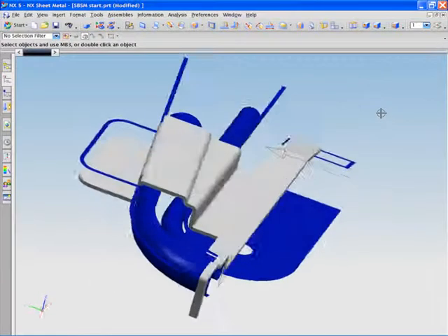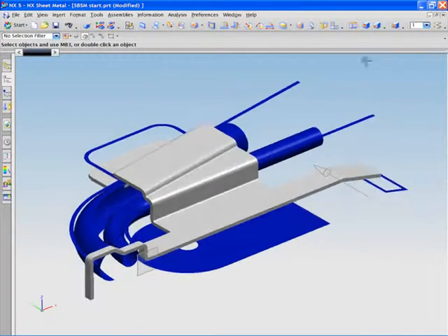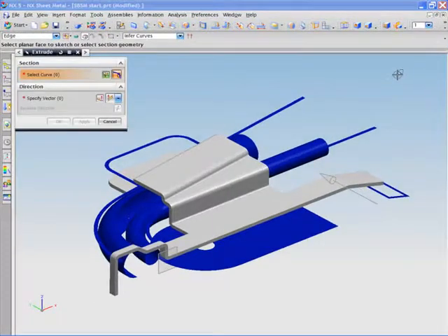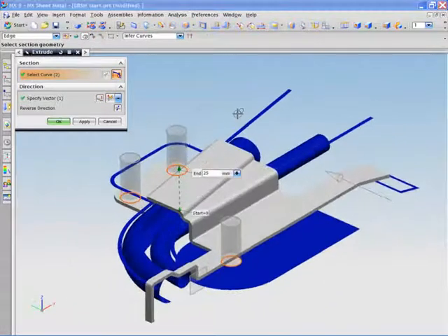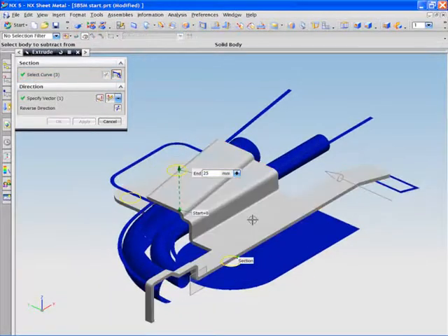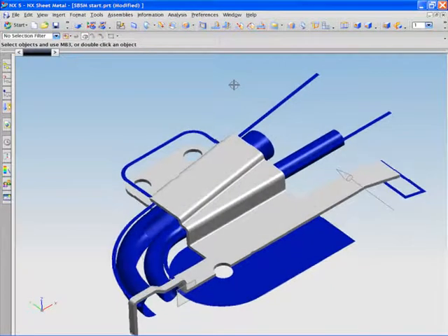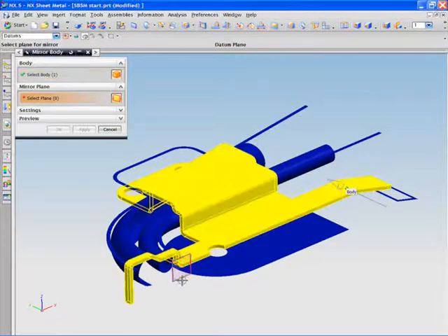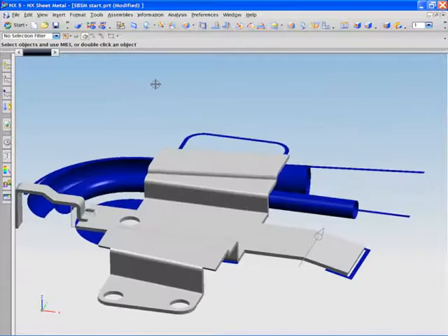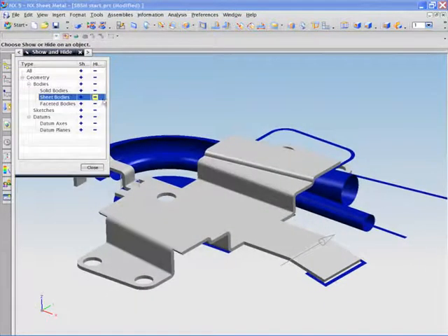Finally, the reference geometry is used to create the fixing holes before we mirror the geometry and complete the bracket design. In summary, what you have seen is that NX can create sheet metal parts easily in the context of an assembly. NX has powerful sheet metal features which enable the design engineer to fully construct sheet metal parts while referencing surrounding geometry.